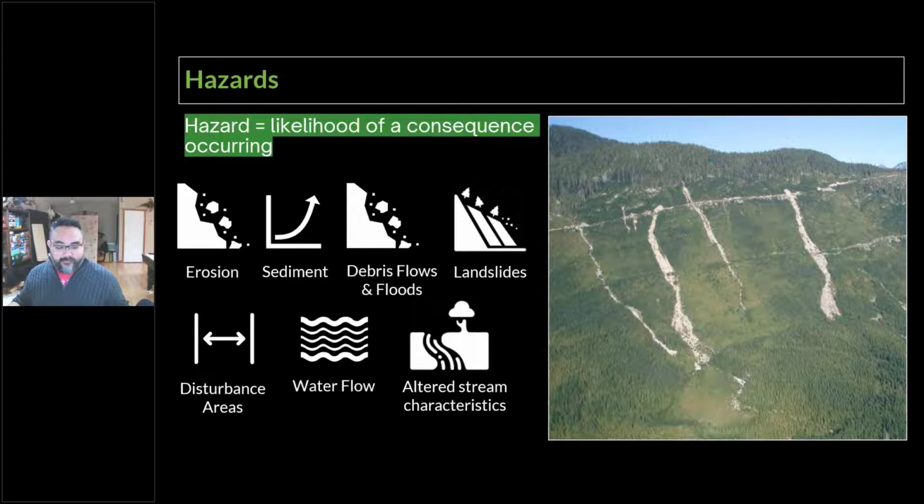And what happens with sediment and debris when it gets in water is it makes the water heavy and erosive. So when we're talking about debris flows, we're talking about adding enough material into that water so it behaves as a really viscous liquid that has a lot of power. And so as these things go, they accumulate things and erode where water itself didn't erode before. And for the purposes of this seminar, the distinction between debris flows and floods is not really critical, but the flood part just acts still more like a high flow that's carrying debris.